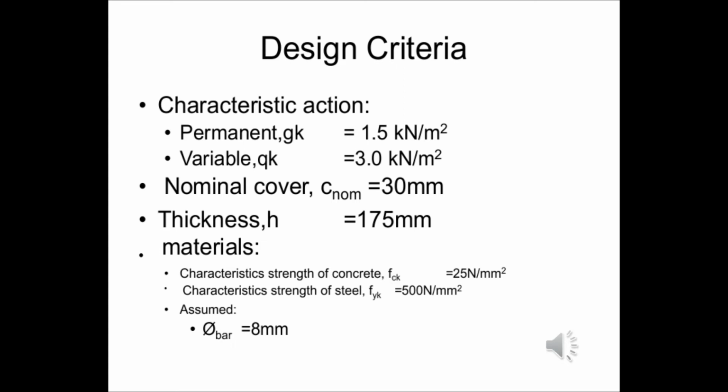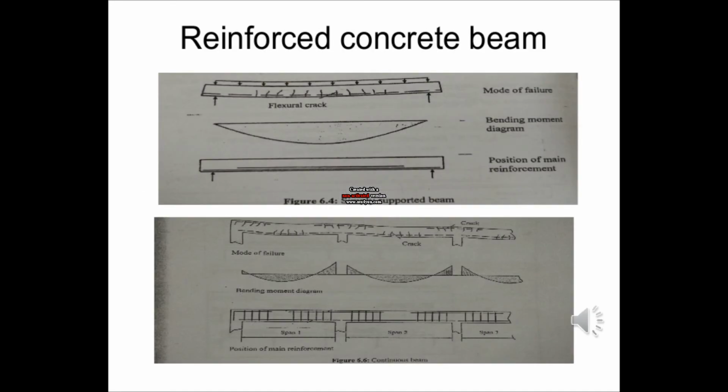A reinforced concrete beam is primarily a structural member that resists lateral loading in bending, shear, torsion, and bond. The design of a reinforced concrete beam must comply with the ultimate and serviceability limit states. As with slabs, beams also have two types, which are simply supported beams and continuous beams. Continuous beams rest on more than two supports and are a common element in in-situ construction.